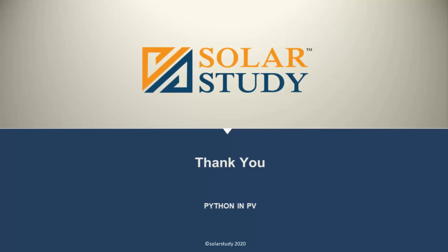We have seen how to do a model IV curve using some field measurement data or lab tested data. So we have generated the model IV curve using these data. In the next lecture, we will look at the standard temperature coefficient condition. Why do we have to use that? There are two reasons. We already saw the data sheet. We will extract that data sheet using the single diode model, and again we will plot different temperatures and different irradiation in the actual model.